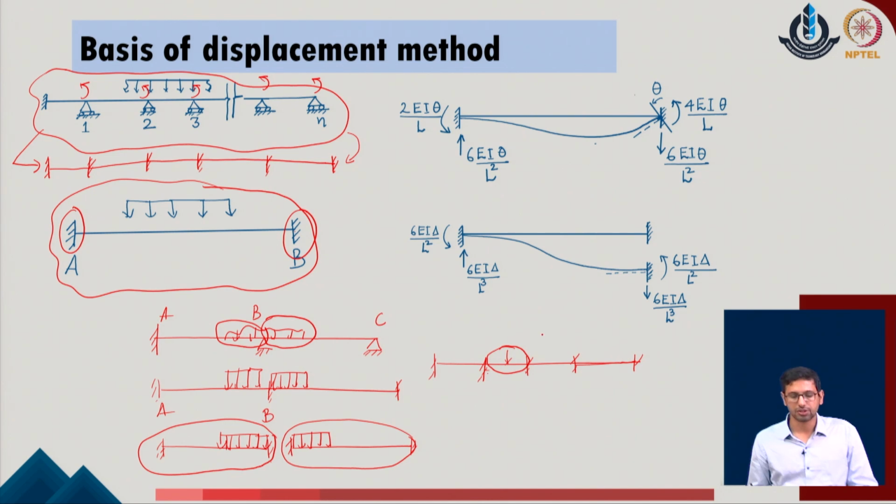As the next part, as we start to release the given reactions of the system, we also recall that corresponding to the amount of rotations taking place in the given system, the fixed ended reactions and the corresponding translational reactions are also notified. In a similar manner, if the system undergoes some kind of translation delta, the fixed ended moment reactions and the vertical shear reactions are also calculated and they are known to the user.